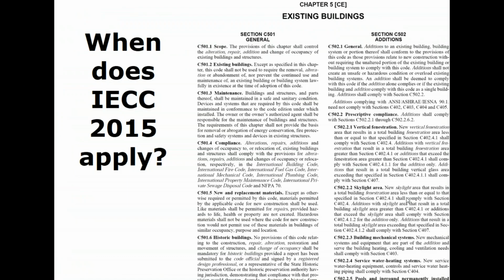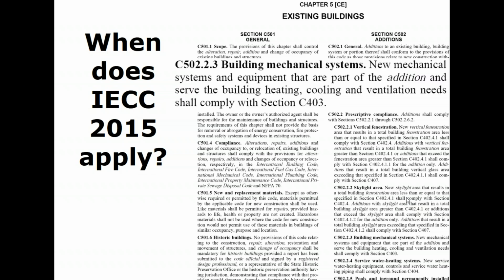So when does the IECC 2015 comply? First of all, if you're in a state or jurisdiction that's following it, obviously. But then in the document itself, there appears to be some things that are accepted. When we start reading the language, those exceptions don't really apply to us on the HVAC side. For example, you'll hear that, oh, you don't have to necessarily do everything in the book if it's just an addition. However, when you go read the section related to additions, it says you must comply with section C403, which is the entire mechanical section.